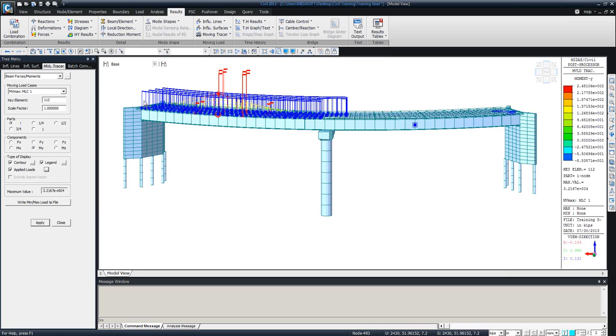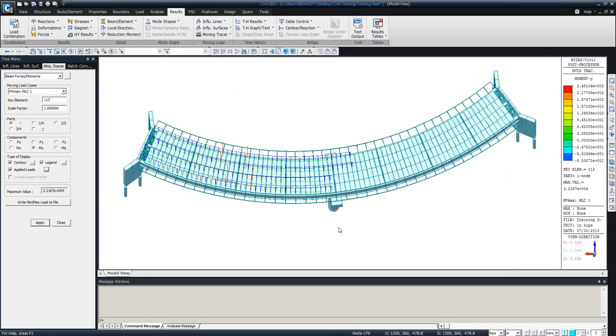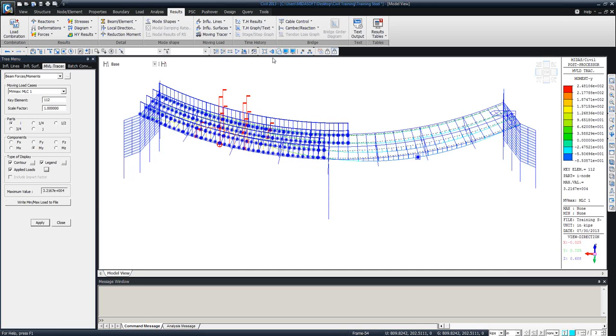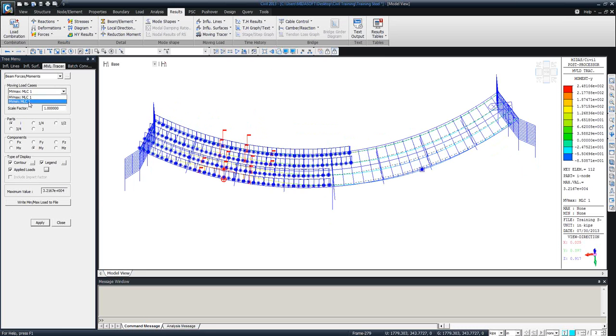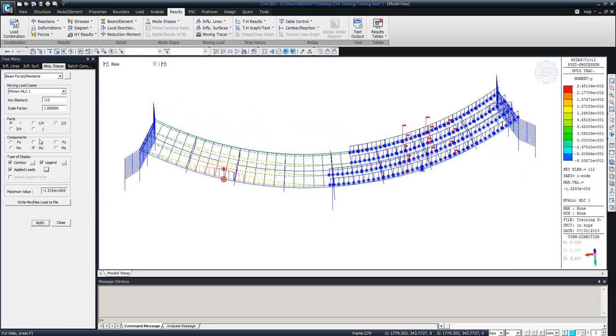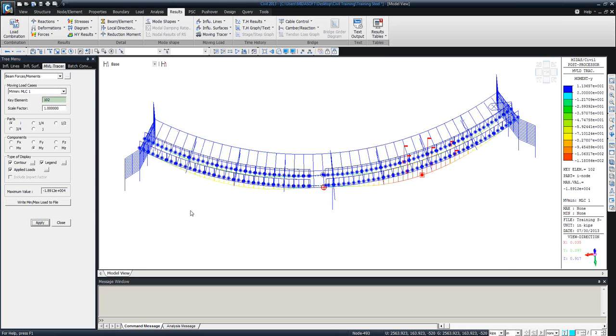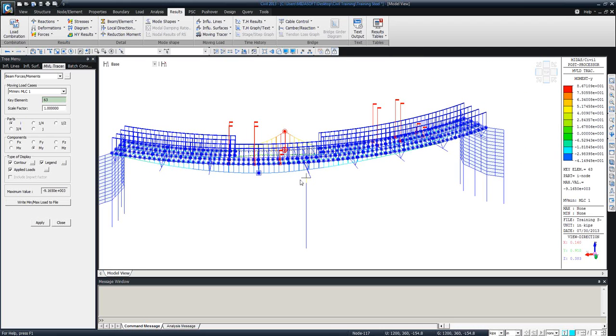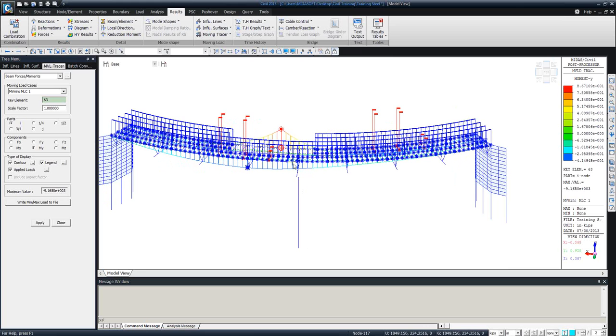All right, that's one option. And if you want to do it again, you can simply change the element number from here to another one. But let's check one other option. For example, for the minimum results, I want to check what will be the result for these elements or the other elements. For example, on this one, the software is applying the two trucks on the two sides of this interior support to provide me with the maximum negative bending moment, or minimum bending moment, in this region.